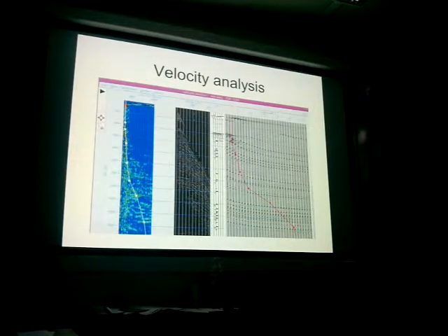All right. So that's how you estimate the stack velocity. And we know from the previous diagram that the stack velocity is even better than the average velocity. The only velocity better than the stack velocity is the one that you got from the check shot. That one is the best you can get without any wells. So you do an estimation using the normal moveout, and you are getting two things at the price of one: you're getting the right geometry and the velocity. Okay?